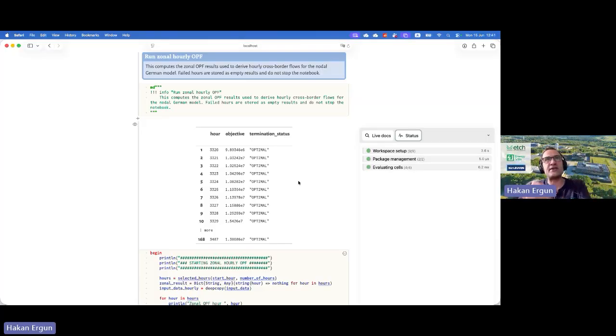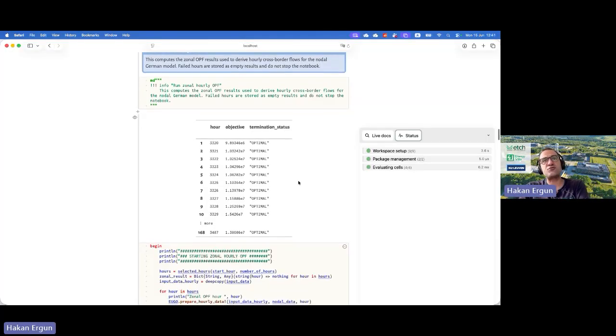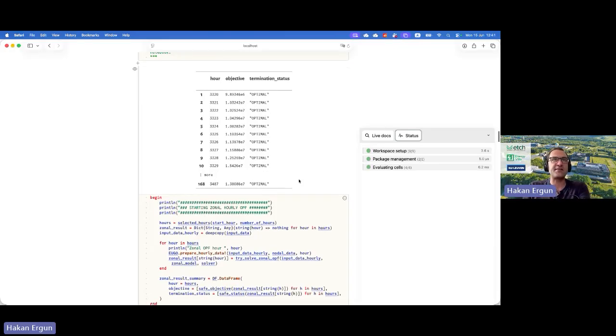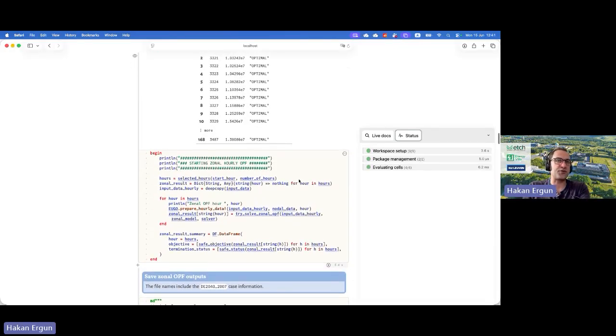And when we are then solving our more detailed optimal power flow model to understand the effect of these 3 embedded links, what we also need to do is to fix the exchange, because now we are changing our grid model. And if we would not fix this particular exchange, then we would get solutions that are not consistent with the market outcome. So for that purpose, also in PowerModelsACDC, a constraint is implemented where, if you have defined borders in your grid data, the interconnecting flows on the borders are going to be fixed.